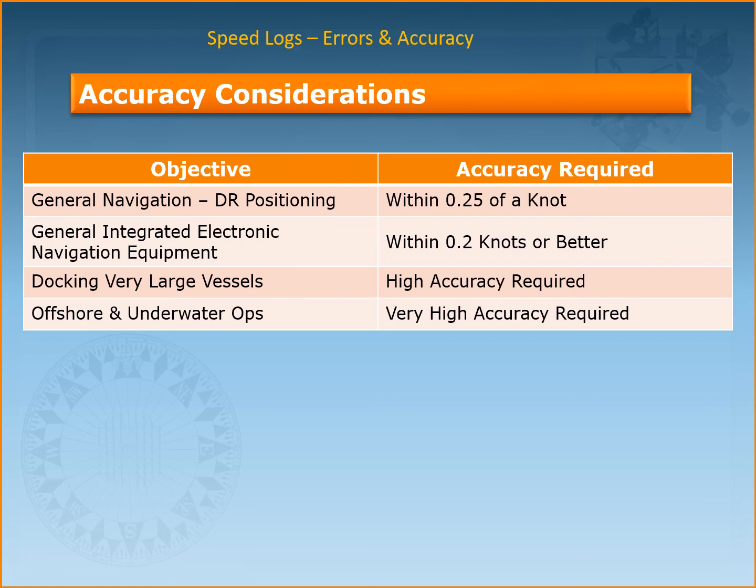Speed information may be presented in either analog or digital form. Where a digital display is used, its incremental steps should not exceed 0.1 of a knot. Analog displays should be graduated at least every 0.5 knot and be marked with figures at least every 5 knots.